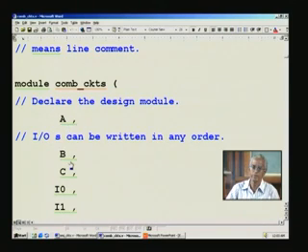And which order you mention is left to you. Whatever is convenient to you, you can do. It's rather a free format in Verilog. And ABC can be an output, or one can be an input or output, or output and input. Any combination that you prefer you can have. So it all depends upon your practice, right? And whatever practice you start with, stick to that, so that it is readable not only for yourselves later on after years of usage when you want to revise the design, but also for others who will be using your codes.